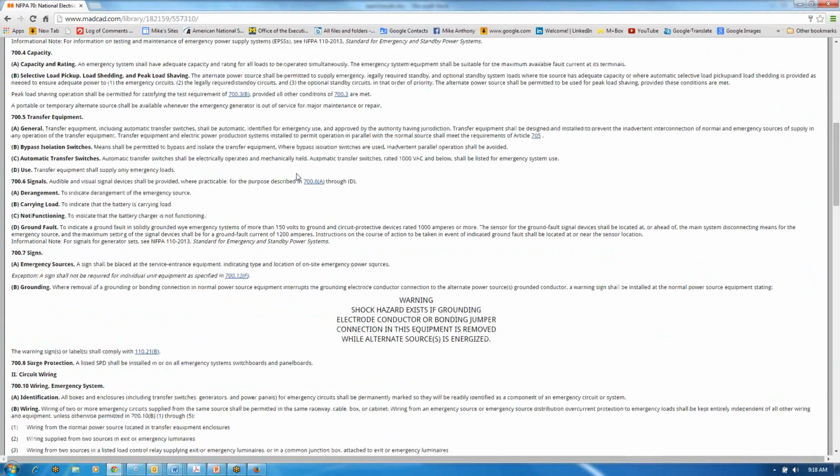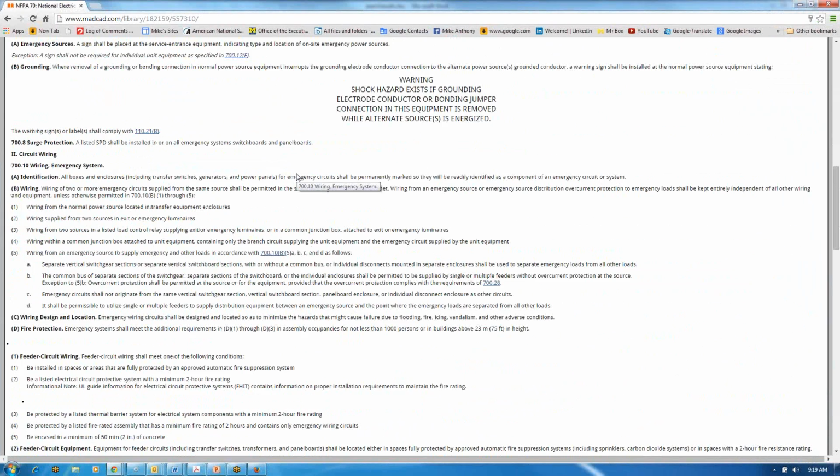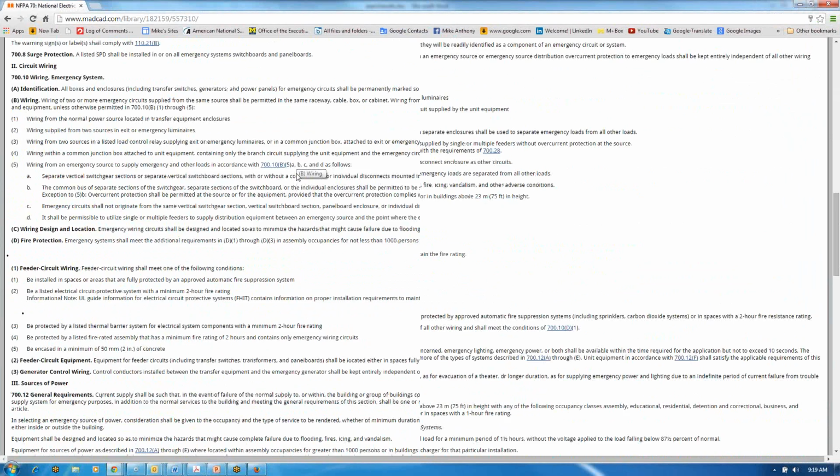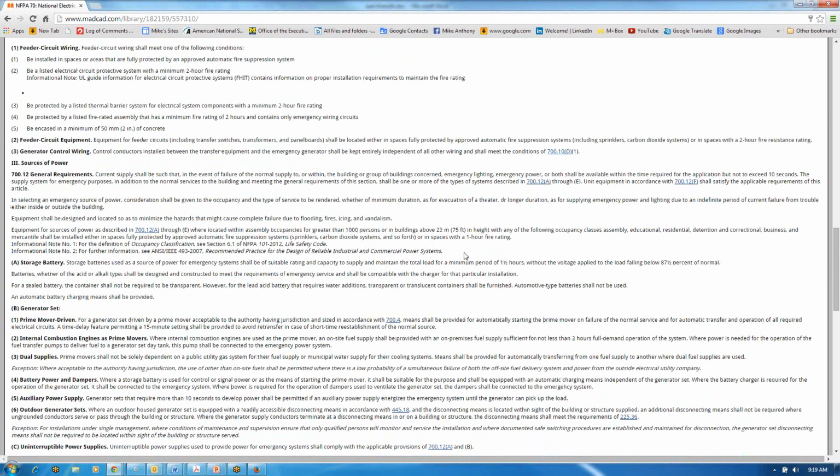So if you don't throw your net a little bit wider in terms of how you model the system, you may mislead yourself into thinking that a second utility feed is truly independent of the first one, and it's just not so. In addition, there are site-specific issues to be concerned about, such as how the two utility feeds are physically brought into your facility. Many times, because of various reasons, they may be in the same duct in the ground, and a dig-in could take both of them out.